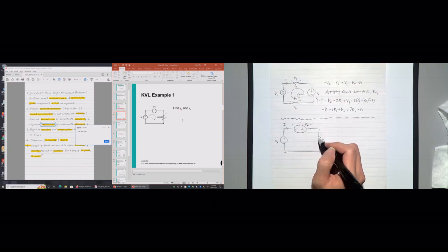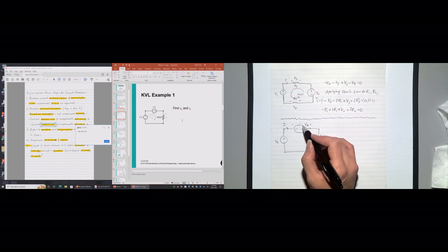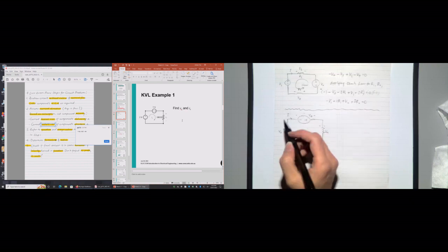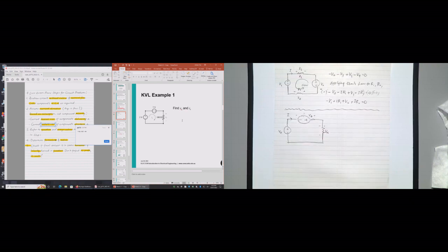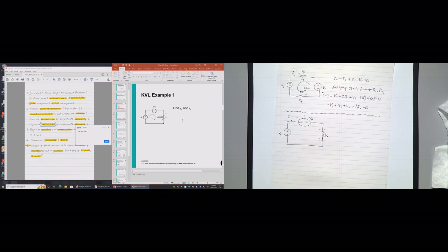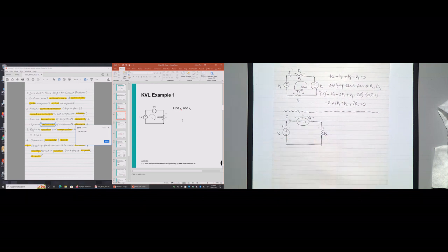Likewise, going down here, this is a load, a component which absorbs energy. So the first point of contact should be positive, negative here. Going down to VA, the first voltage source, this is the component that delivers energy, so this must be my positive terminal and this must be my negative terminal. Apparently this is easy because it coincides with the figure itself. Now we can refer to the question and assign all the values in accordance with our little diagram here.